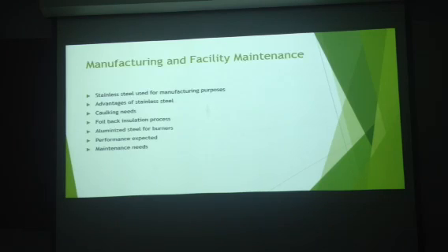Whereas for wood burners, the amount of junk wood that is being used has to be minimized. For the maintenance needs, the authorized contractor should have a monthly checkup regarding whether the system is operating efficiently. The HVAC contractors should be conducting annual inspections for the gas furnaces and are required to fill the maintenance and log sheets by stating the conditions and corrections that are required, if any.